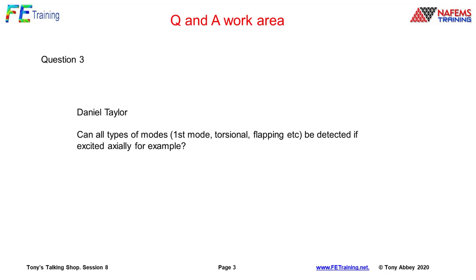If we do a response analysis, such as my gantry here that we're seeing on this particular screen, I'm only going to excite those modes which are of interest in that particular response, which are going to be the out-of-plane modes. Notice that on the previous slide, we jumped from mode 1 to mode 4. Mode 2 and mode 3 are just not interested in what we're doing.